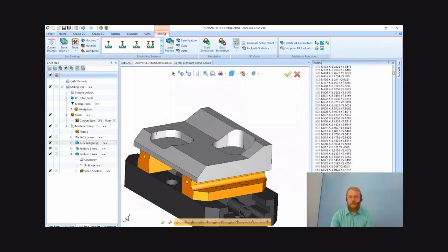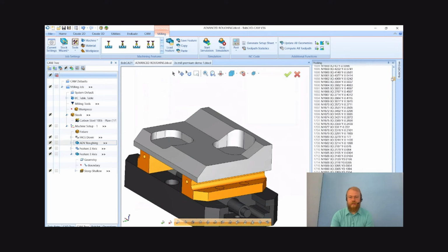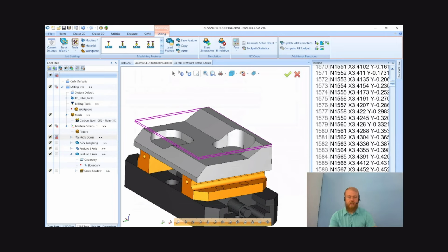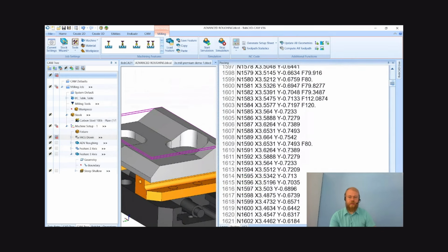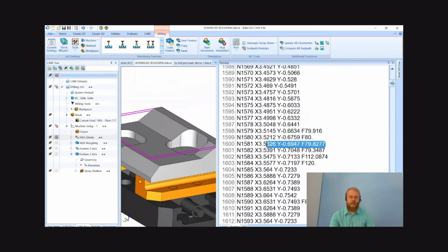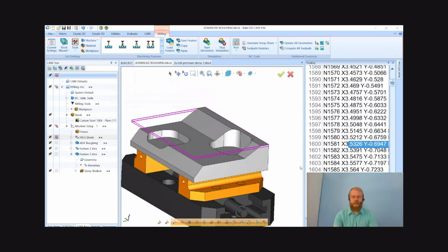You can take a look in the roughing operation here in the G code. If you guys can see it here, I'll expand it a little bit larger so that when it's getting into a corner here, you can see on each line of code, it will set a different feed rate to keep a constant chip load. All the way up to 120, all the way down to 8 inches per minute. It's only going to slow down a little bit in the corners there. But yeah, a great way to control your feed rates there with your adaptive feed rates in the 3-axis Pro tool paths.